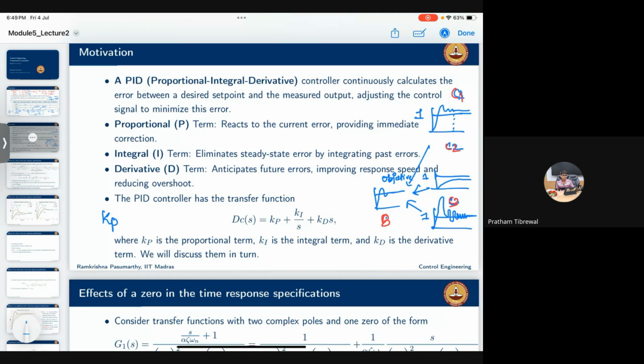I'm going to add one K is equal to KP, that we are calling the proportional constant. Some random number, proportional. Previously I have kept it as KC, now I'm calling it KP, there is no difference. Second thing, I'm going to put one gain KI, where I'm going to integrate this KI gain with respect to time, for all the time the system is on.